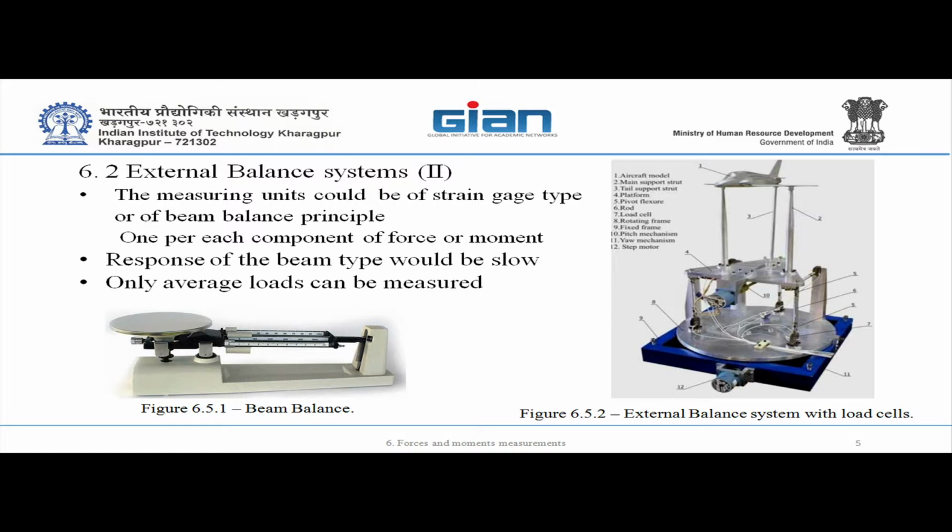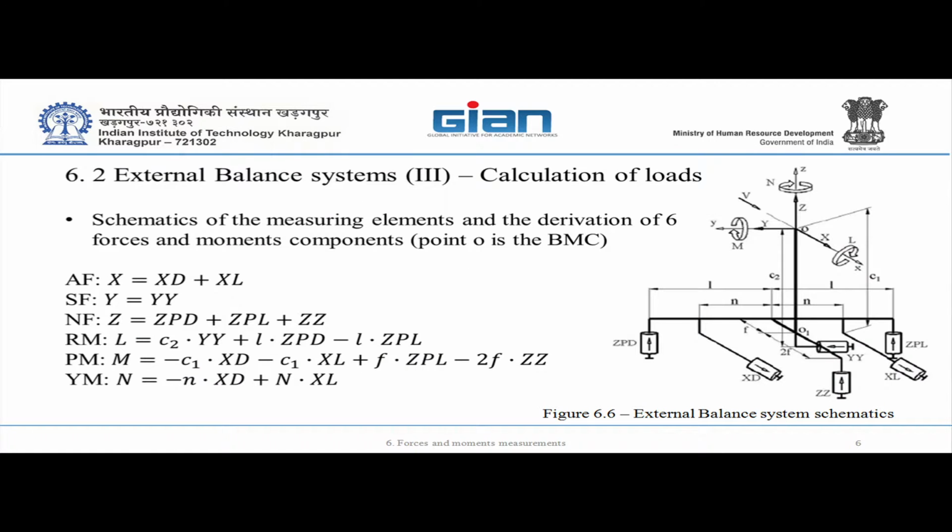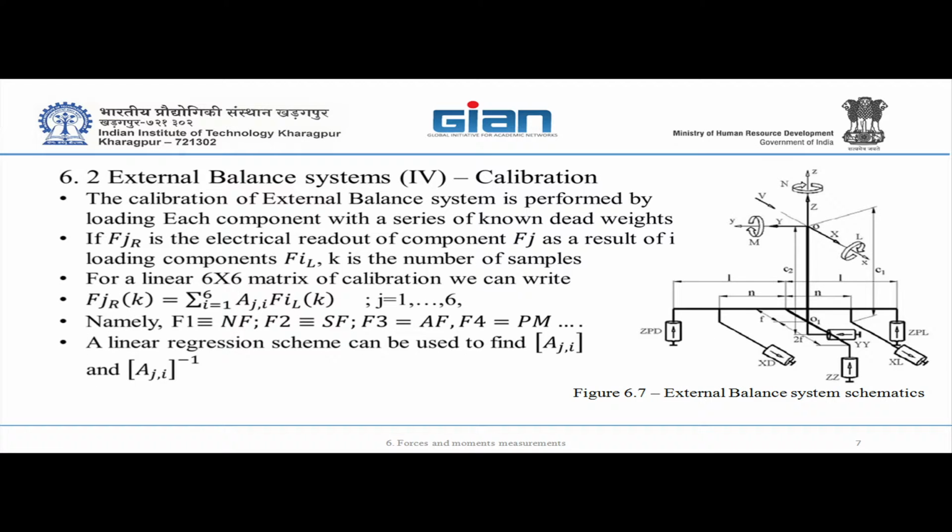External balance calibration, I must admit, rarely you see people calibrating this kind of balance. It's a very tiring mission because you have to build a specific frame in order to calibrate your balance. You have to load every axis according to a plan.